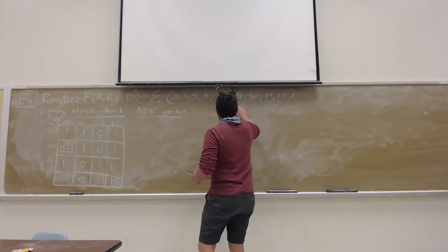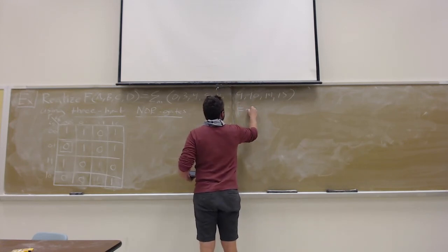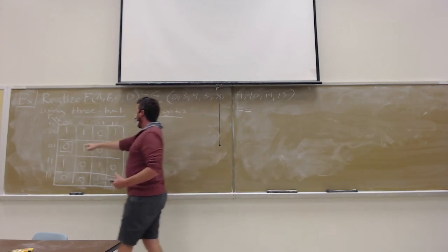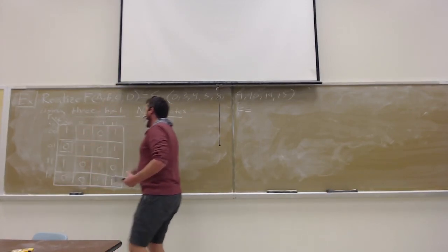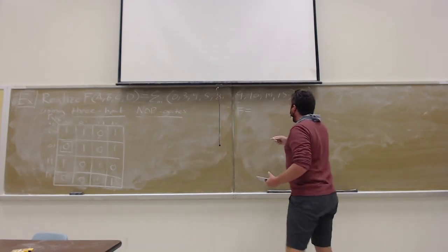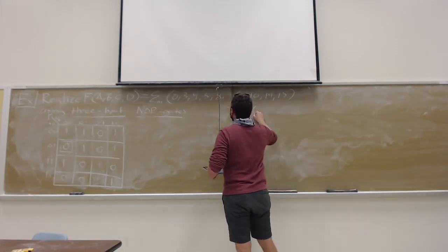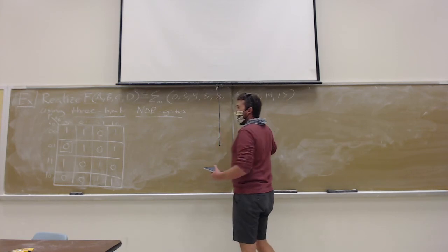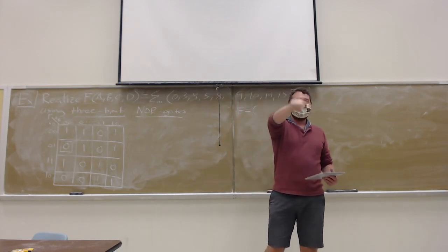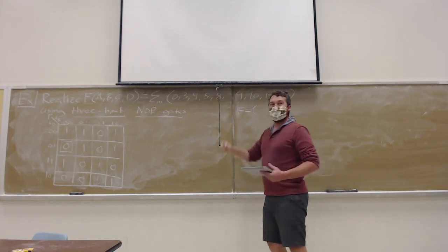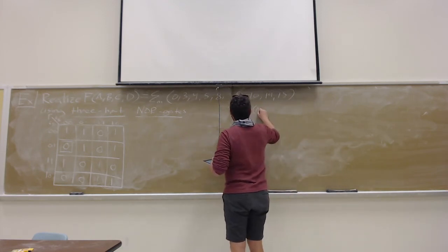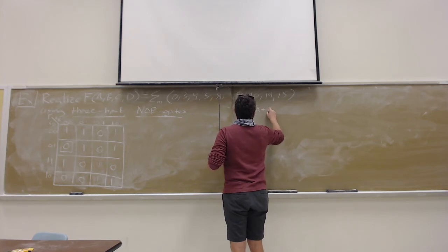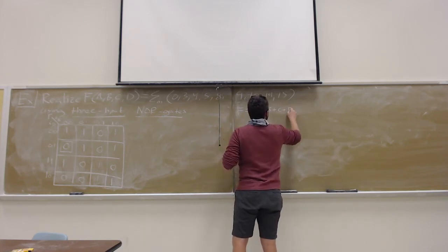All right. So let's see. We got F. So what does this get us? It's 0. It's a max term. It's in 0, 0, 0, 1. Means we're going to have what? A naught, B naught, C naught? No. Good. Remember it's flipped over because we're doing the max terms. So 0, 0, 0, 1 is going to get us A or B or C or D prime.